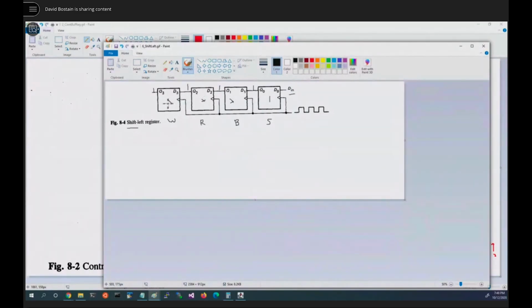But after we have sprayed the car, we need to move it 1 to the left. A new car may have arrived, so there may be a 1 waiting to come in. If it does, this 1 on the clock will get moved here. This guy will get moved in here. These X's will be here, and one of the X's we had, just like the first one, will just be dropped out on the floor. Keep moving. If there's ever no car to come in, there'll be a 0. 0 gets moved in, the 2 1s get moved over, whatever was here, until we fill it up, and then whatever we put in keeps dropping out the end. So we can put a number in, shift it in, and as we go, it's going to constantly be moved 1 position to the left.